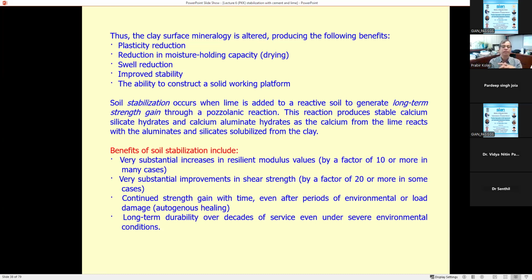Sometimes, when the soil is very soft, there are 2 methods: a dry mixing method, the shallow mixing method, and the deep mixing method. Sometimes when the soil is really soft, you use cement or lime and mix it together. With shallow mixing, the strength increases a little bit, and you cure for 3 to 7 days. Then when it is strong enough to hold the equipment, such as a boring machine, you go there and make a column, for deep mixing, a strong column of either cement or lime. So, deep mixing column.